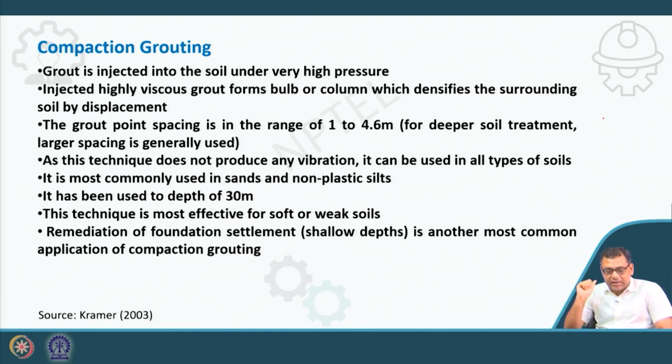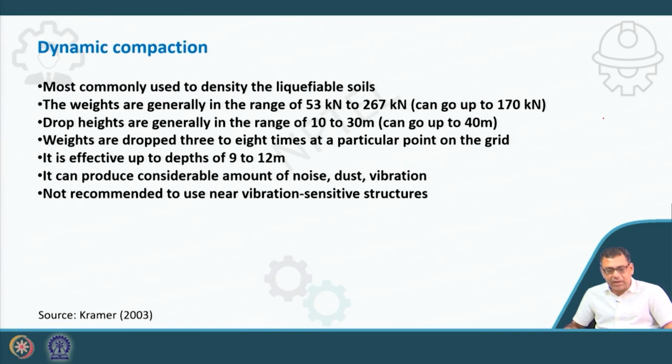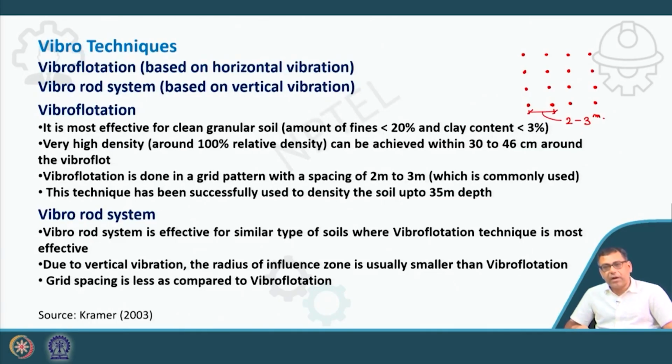As this technique does not produce any vibration, it can be used in all types of soils. In the vibration techniques we discussed previously, like vibro compaction, blasting, and dynamic compaction, vibrations are produced.